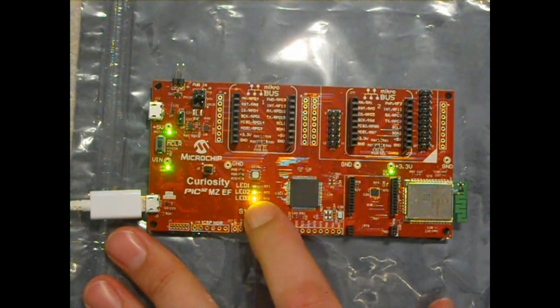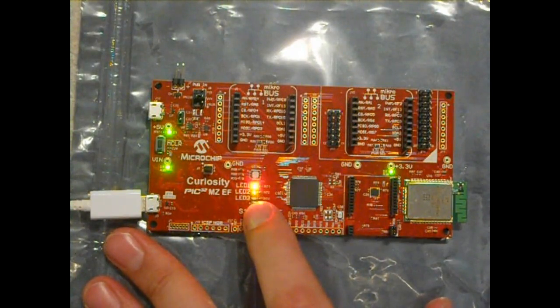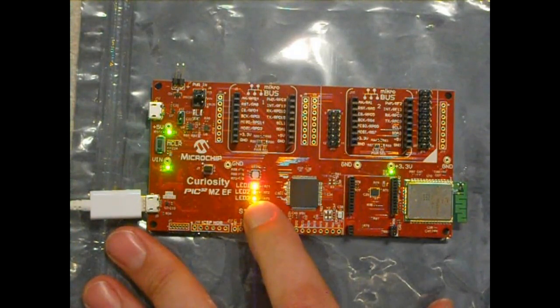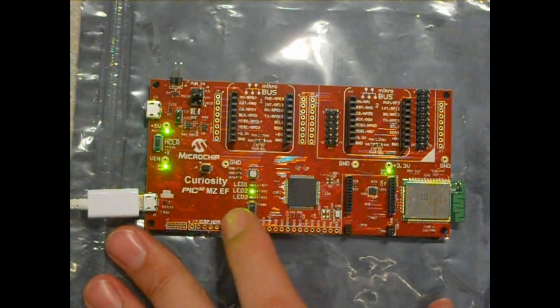And the reason is that it's flashing at half the speed of the other flash, because the yellow LED is turning off, waiting, then turning back on, and then waiting, and then the button code is running. So the button code only has the option to turn on or off once every while loop, where the yellow LED is actually turning on and off in one while loop. So that's why you have the speed difference here of the flashing.